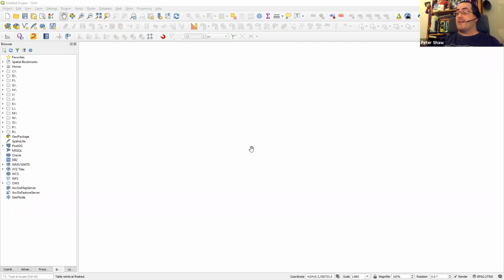And I have this very, very simple file that just has this single point, nothing else. And when I zoom to layer and I zoom in my drawing so that I've got that point right there, and that point is about the size of my hand cursor, I know that I'm zoomed right in and I'm down to about 1 meter per half a centimeter, something like that. You follow? And then that way, when I pull in some tile imagery like that, I'm only pulling in maybe 10 meters by 10 meters if I'm lucky.